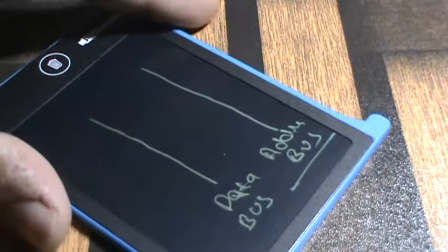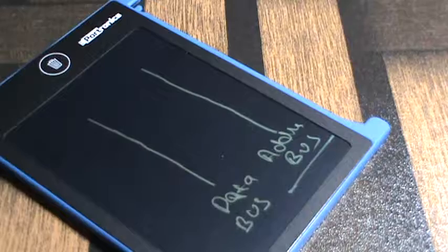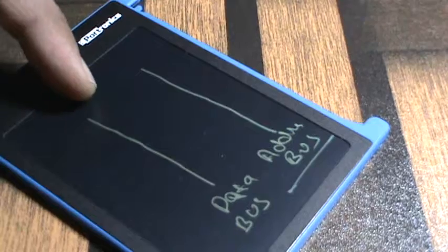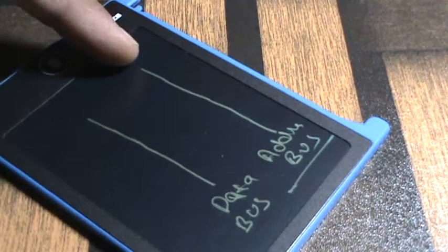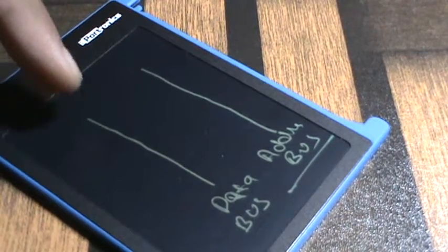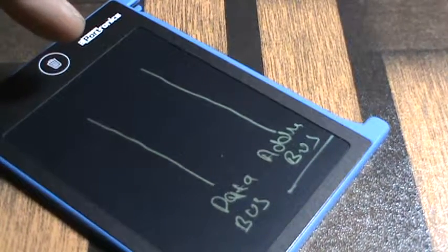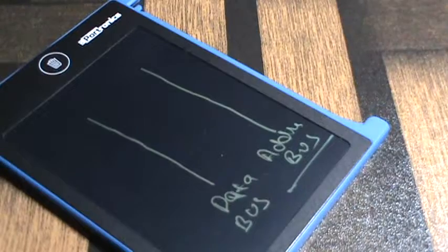So let's say we want to display some character on our monitor, then it's going to have some address values assigned to that particular monitor. And whenever our CPU sets that particular address onto our address bus with some particular data on our data bus, our monitor activates, receives that data, and displays it on the monitor.